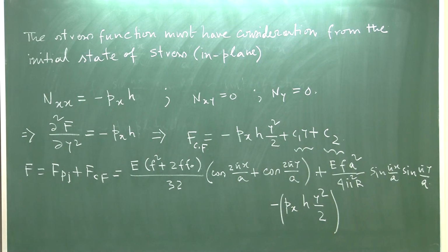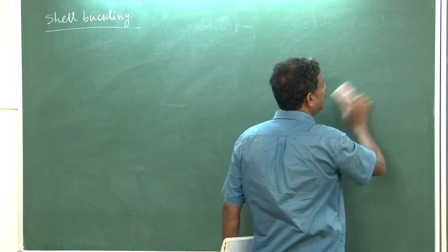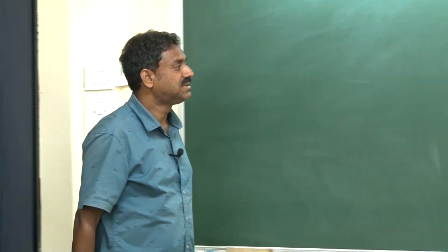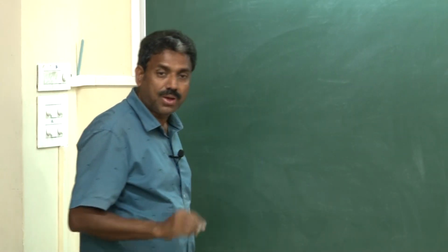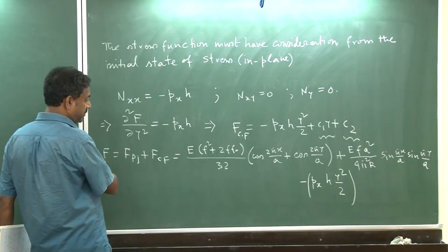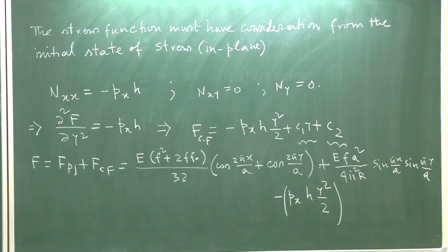Well, which equation have we made use of? We have satisfied stress compatibility, we have satisfied the boundary conditions while assuming this kind of solution, right. Boundary conditions were satisfied, compatibility was satisfied to obtain the particular solution for the stress function. The only thing that is remaining is the equilibrium equation. So, we have to solve the equilibrium equation, but do you think that if you directly substitute the stress function as a function of x y, and substitute for w and w0, it will satisfy the equation?